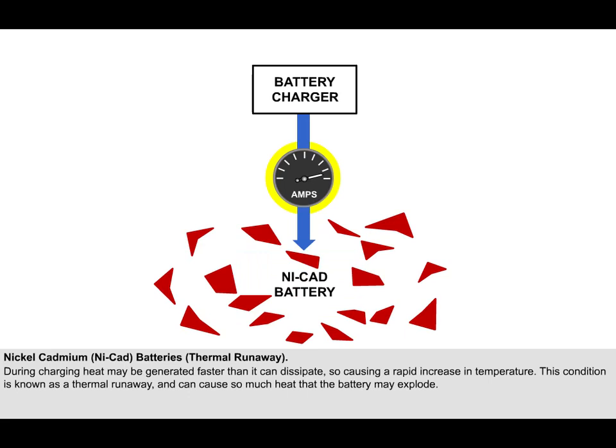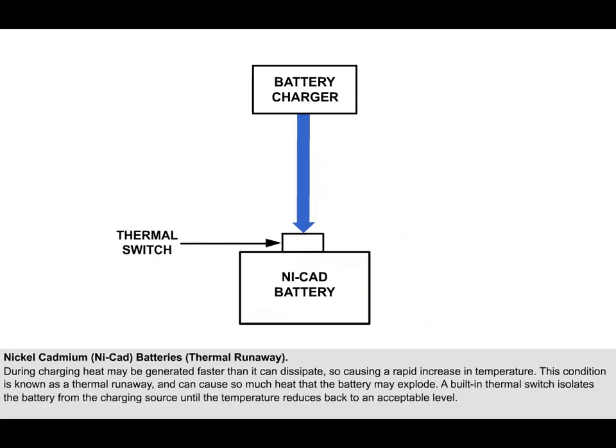For this reason, the charging of a NiCad battery must be closely monitored. A built-in thermal switch monitors the battery temperature and operates at a preset temperature, isolating the battery from the charging source until the temperature reduces back to an acceptable level. There may be an indicator light on the flight deck to alert the pilot when the temperature switch operates.